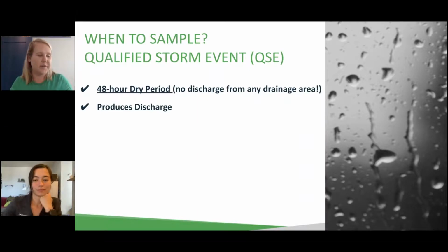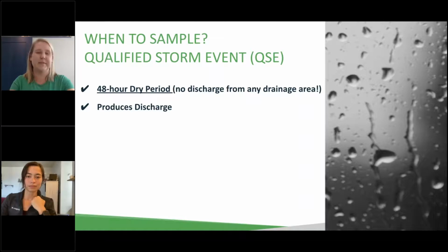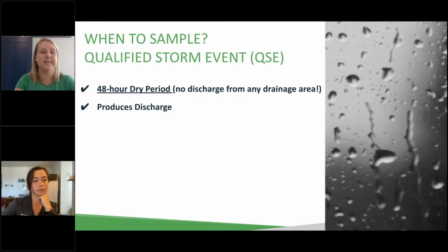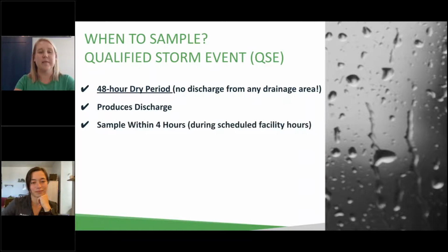You know, here in Southern California, we get a lot of rain that oftentimes doesn't go anywhere. That is not a qualified storm event. You don't need to scrape the rain off of your pavement and send it in for a sample. It has to freely, willingly leave your site to be a qualified storm event. And then once it does start leaving your site, you want to get that sample within the first 4 hours of discharge. This is if it starts discharging during facility hours.